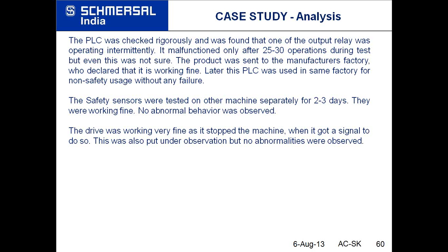Why I am saying this: there was some sluggishness in the output relay, but this was not regular. This was intermittent, and you never know when it will operate sluggishly.